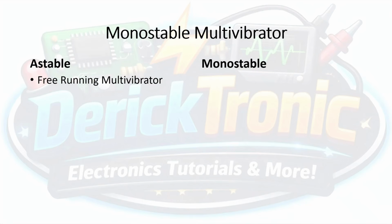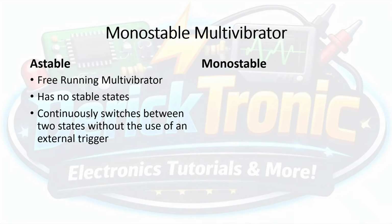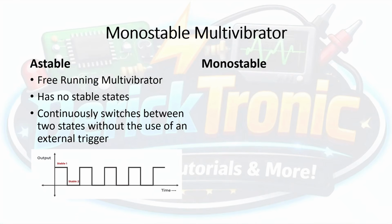It's called a free-running multivibrator. It has no stable states. And as you saw in the previous video, the output continuously switches between two states, the on and off state, without the use of an external trigger. The waveform looks something like this.